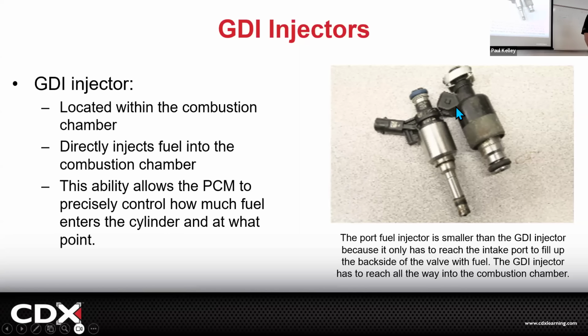We've also seen where these injectors can fail, but they're a little hard to diagnose because you can't just put a fuel pressure gauge on it. You're looking at the fuel pressure sensor. And then, you know, if you can check compression and that's good and spark is good and it misfires, you're kind of like, yeah, I think it's the injector, but it's very hard to actually test these.